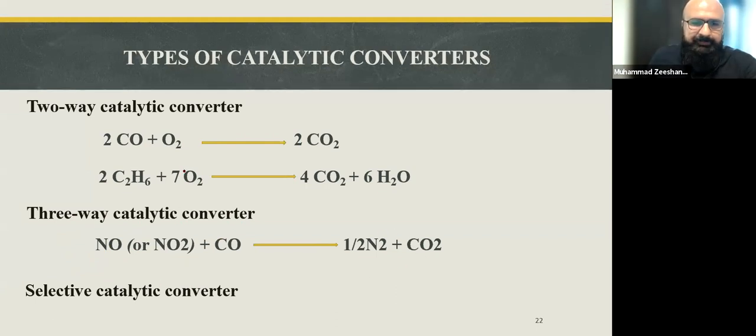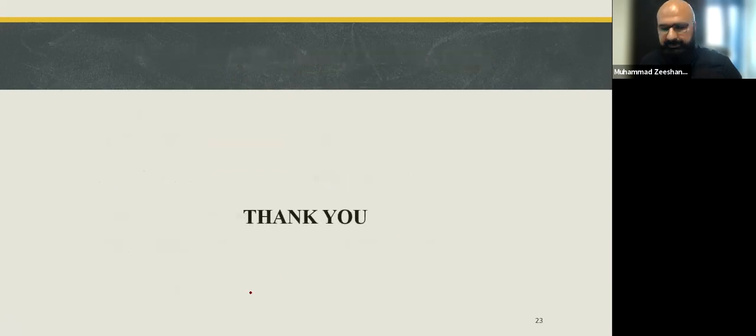And there is a third type of catalytic converter, which is called the selective catalytic converter. Normally we use it with diesel engines, and that converter is designed to handle one particular gas at a time. Normally we deal with, for example, NOx, and we reduce NOx into nitrogen and less toxic gases using a selective catalytic converter. With this, I finish my presentation.